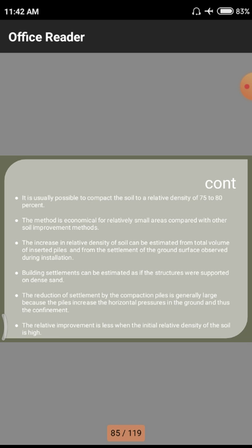Why? Because it is not a free space. We need to dig a huge amount of land. After the digging is over, we need to pour some amount of free particles. After pouring the particles, we need to use vibrators and other compaction equipment to strengthen the soil, so that we have some amount of disadvantages. Due to those disadvantages, the remaining 20 to 25% of soil is not purely compacted, and we are having a compaction factor only up to 75 to 80%.